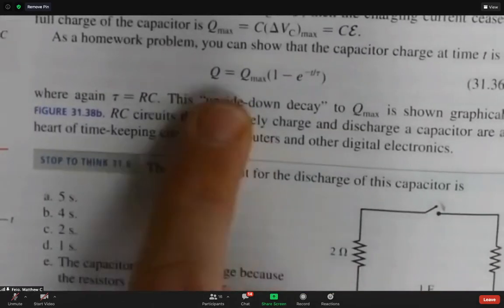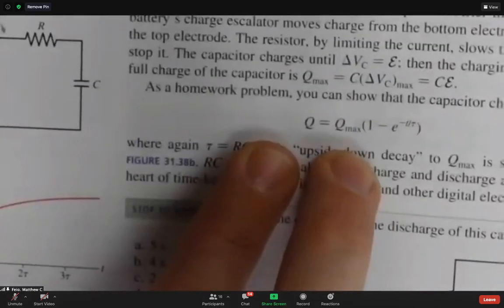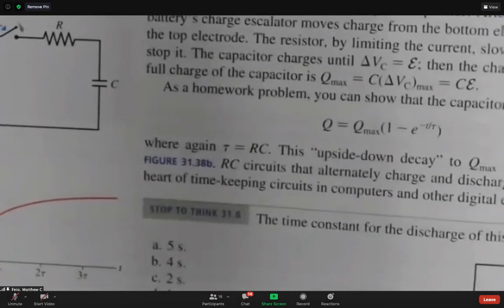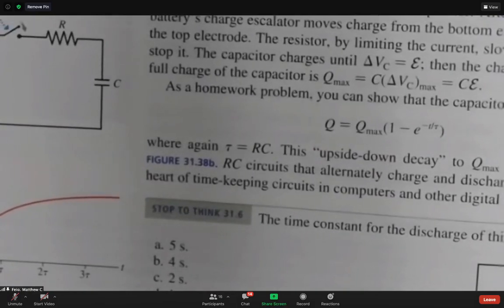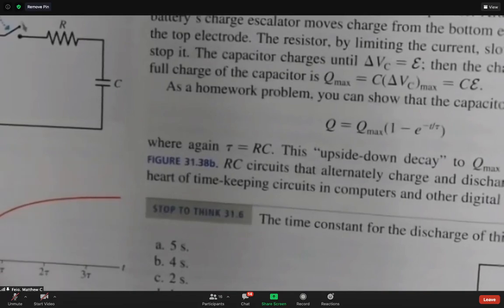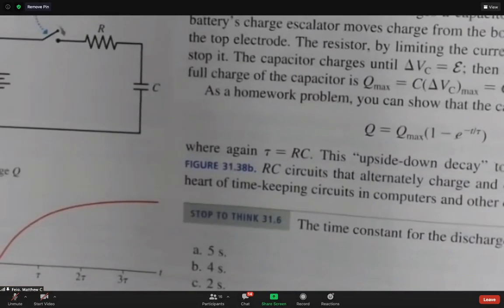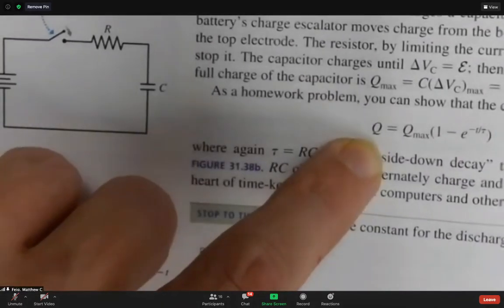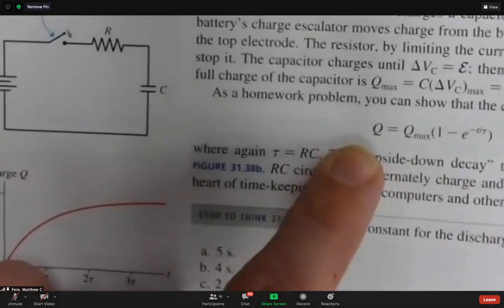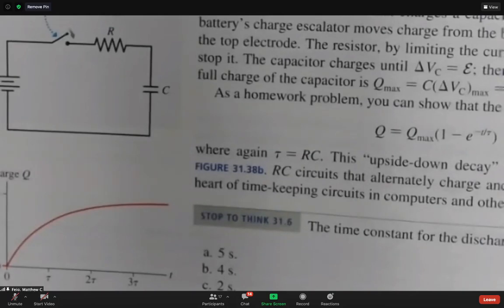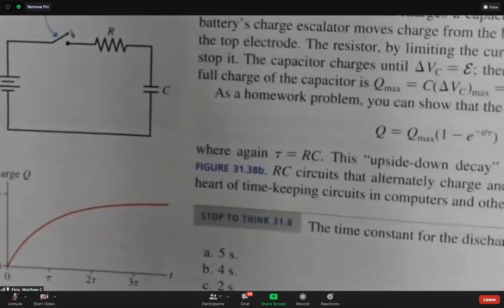And then basically, if you divide both sides of this by capacitance, that turns charge into voltage, and we could just write V and Vmax. And then you could kind of work it out. Mainly algebra. There's a V off with a T off, and there's a V on with a T on, and we want to find the time difference, T off minus T on, or maybe on minus off, I should say. But anyway, subtract them. Do some algebra. All right.